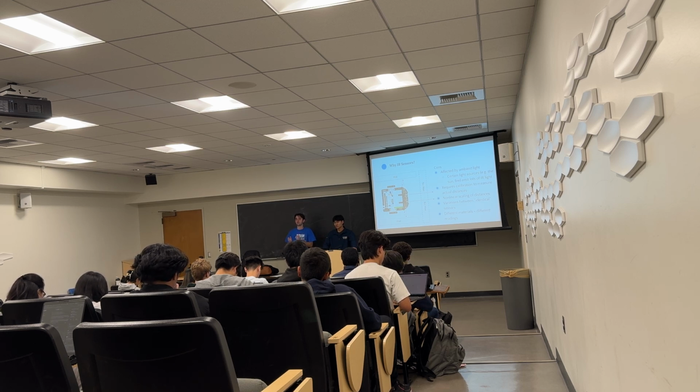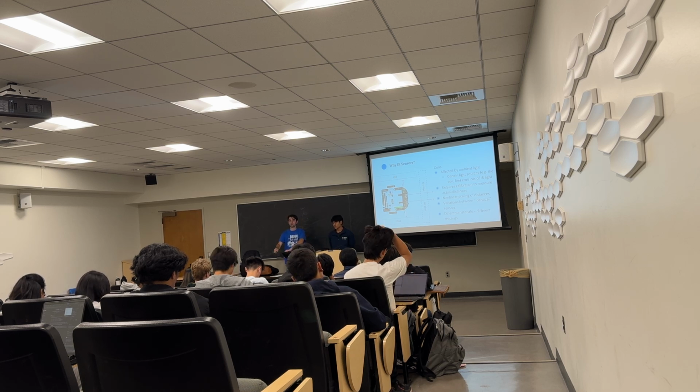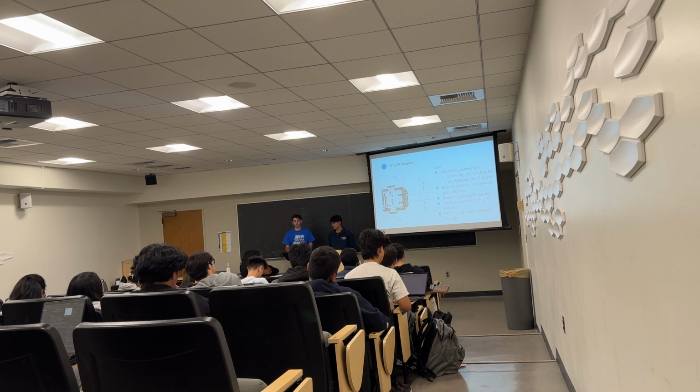If we put our mouse 1 inch from the wall and get a value of 2000, we then program the mouse so that if you get a value of 2000, that means you're 1 inch from the wall. It doesn't actually mean that, because another sensor on the same mouse could read 700 at an inch away. So they're not precise measurements; you have to define what they do. And then there's the same thing mentioned earlier about the nonlinear scaling of distances.